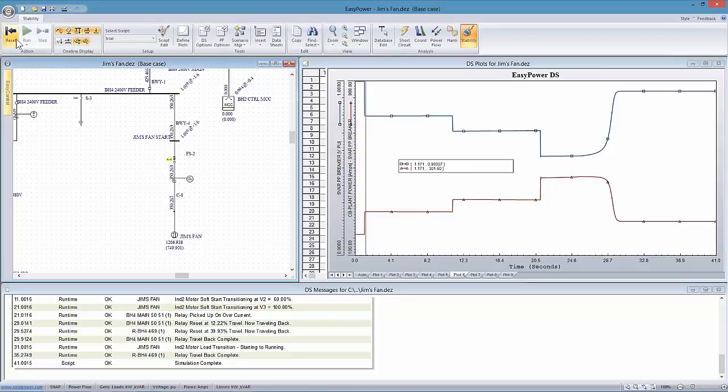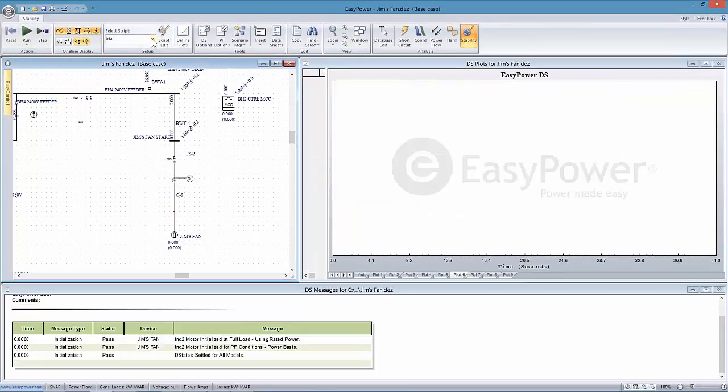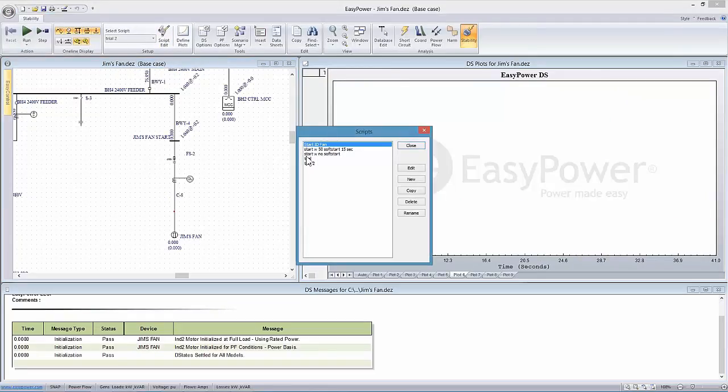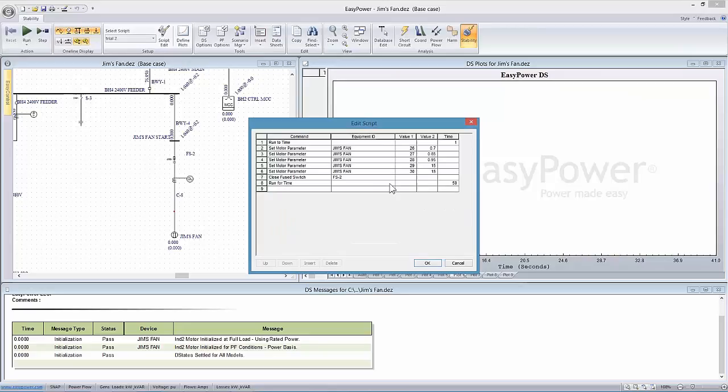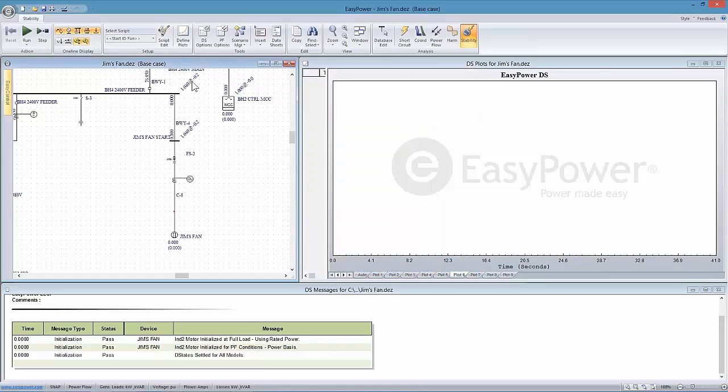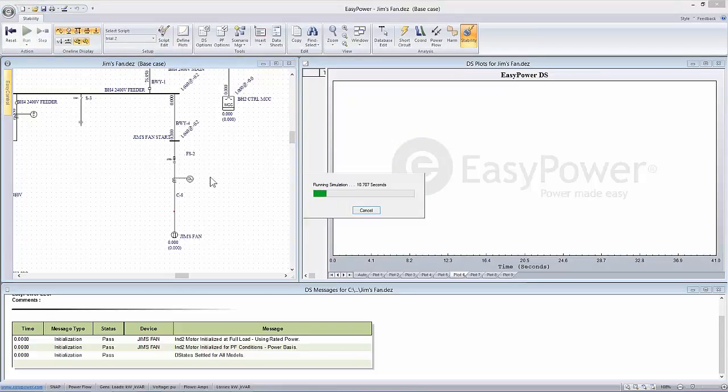And so let's see what happens if I stretch that a little bit longer. Let's go to trial 2. And you can see that what we're setting here is I'm going to 70% voltage on the power start, 85%, and then 95%, and set those each at 15 seconds and see what happens. So let's see if that gives us any breathing room.